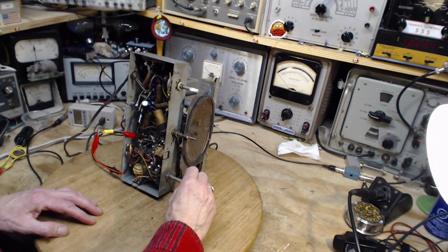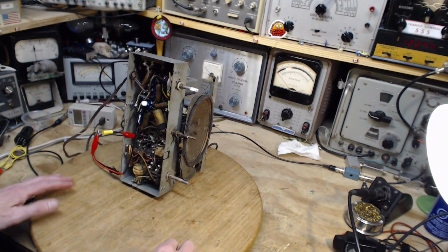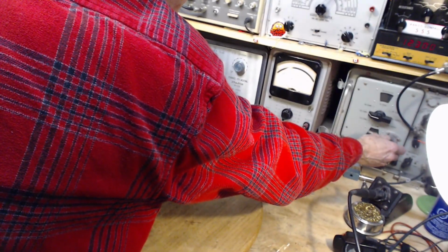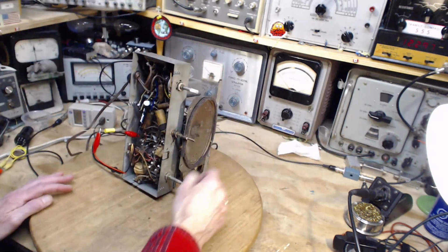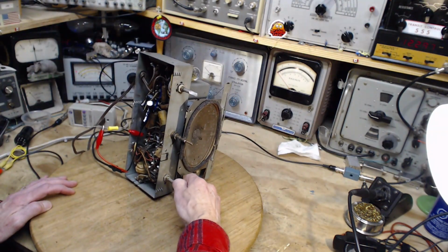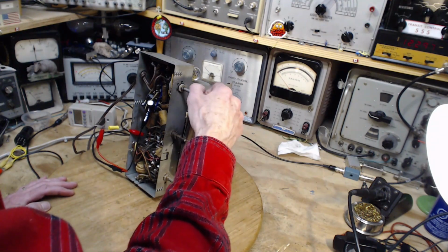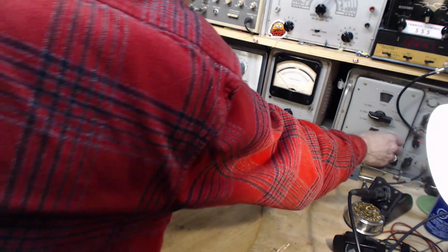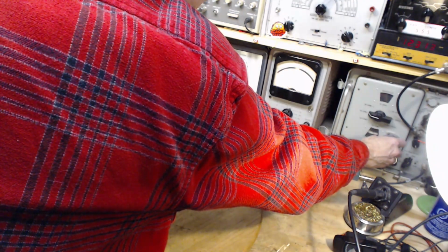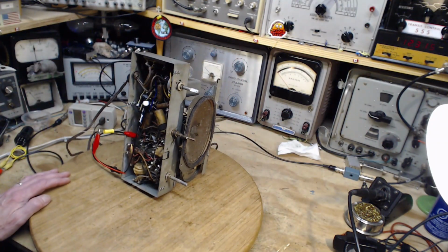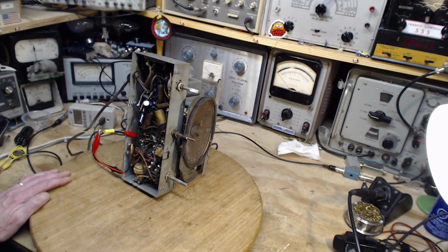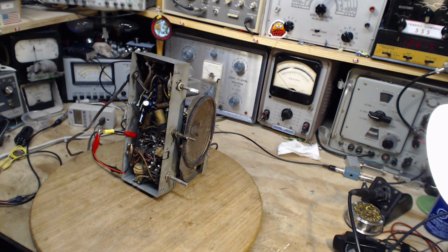Nobody home. That could be, again, a little frequency shifty thing has happened here. Let me just... No. So ditching that for whatever reason. Why so weak? So a weak local oscillator would be the next thing to check on. Okay, that's the next thing we'll do then.